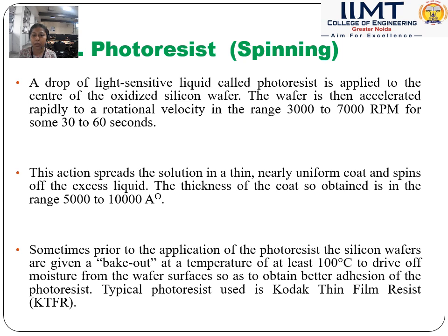Sometimes, prior to the application of photoresist, the silicon wafers are given a bake-out at a temperature range, and then excess moisture from the surface can be removed for better placement of the photoresist. Typically the photoresist is coated as a thin film.